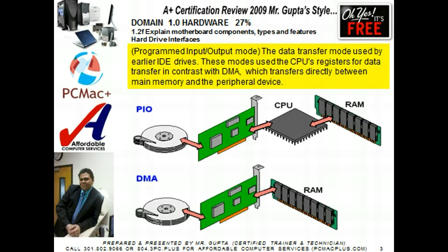If two hard drives share the same parallel ATA cable but use different standards, both drives will run at the speed of the lower drive, unless the motherboard chipset controlling the ATA connections supports a feature called independent device timing. Most chipsets today support this feature, and with it, the two drives can run at different speeds as long as the motherboard supports those speeds.